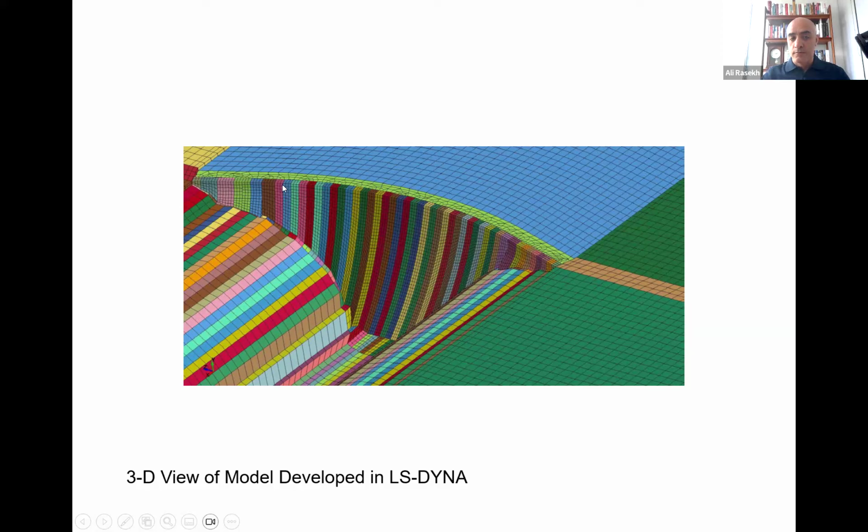And between them is what we call a contraction joint, so that in wintertime they can shrink and in summertime they can expand. We don't want any overstress or tension to happen in winter. Therefore, we put contraction joints between them. So the joints between monoliths are real.